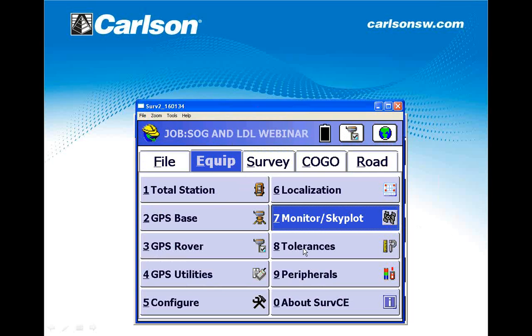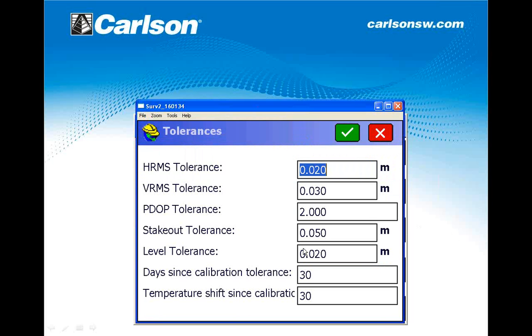So checking into tolerances, here you can see the level tolerance. This is the new one. The leveling tolerance, you set it in meters, linear units. My setting is 2 centimeters. This means my tolerance for deviation from the vertical, I mean the phase center deviated from the vertical of the line of the ground position, is set to a maximum of 2 centimeters right now.